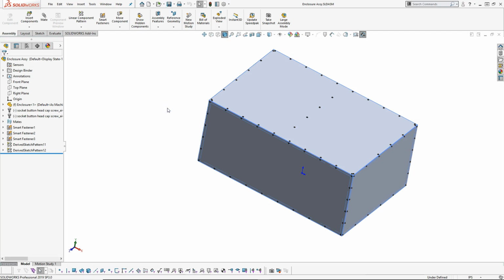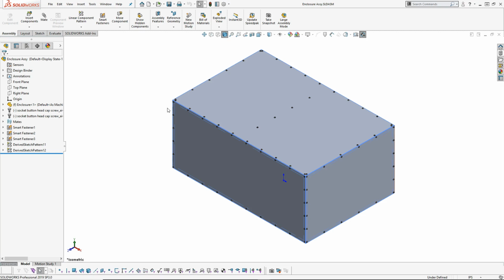So one of the things with the multi-body part is everything's tied together and we've mixed the weldments and sheet metal. I mentioned early on that if it was going to be an issue, I would do the weldment as a part, or a derived part, or a new part, so it has those references to the 3D sketch that's in the assembly. And then in that case, I might only need one wall, and I could mate those and reuse them rather than have individual items.